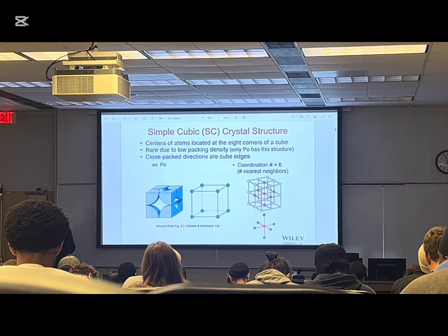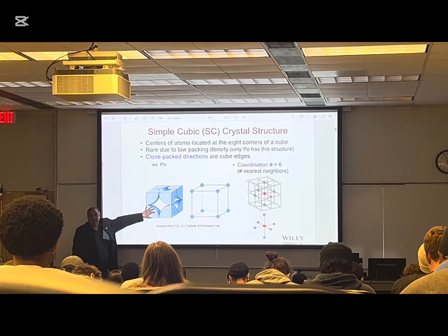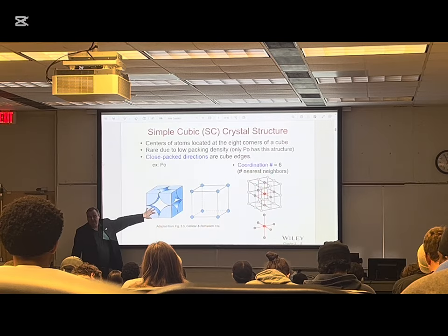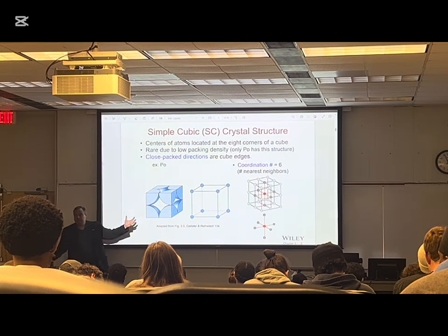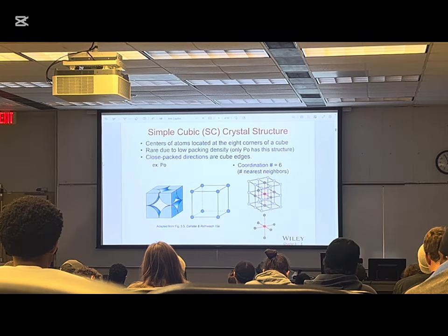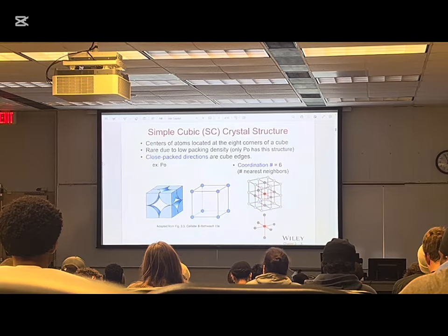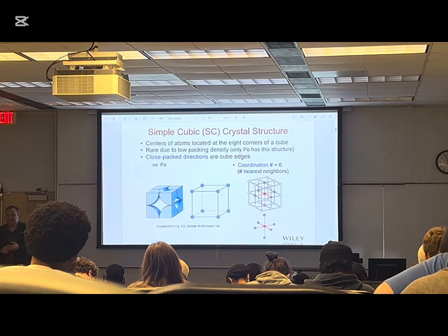But what is the volume of the atoms in this unit cell? You see, because we have spheres here, and this is 1/8 of a sphere. You see that? So if you think about it this way, if you take all these pieces, which is 1/8, and put it all together, then how many whole atoms are we going to have? Just one. Do you get the concept? It's not that hard. So let's figure this out on the simpler one before we move to a little bit more complicated ones. That's the idea.